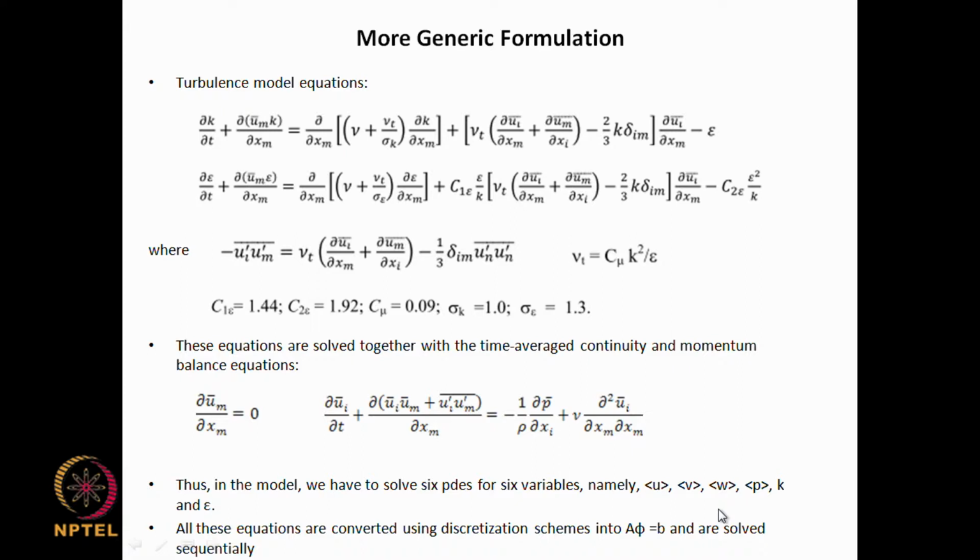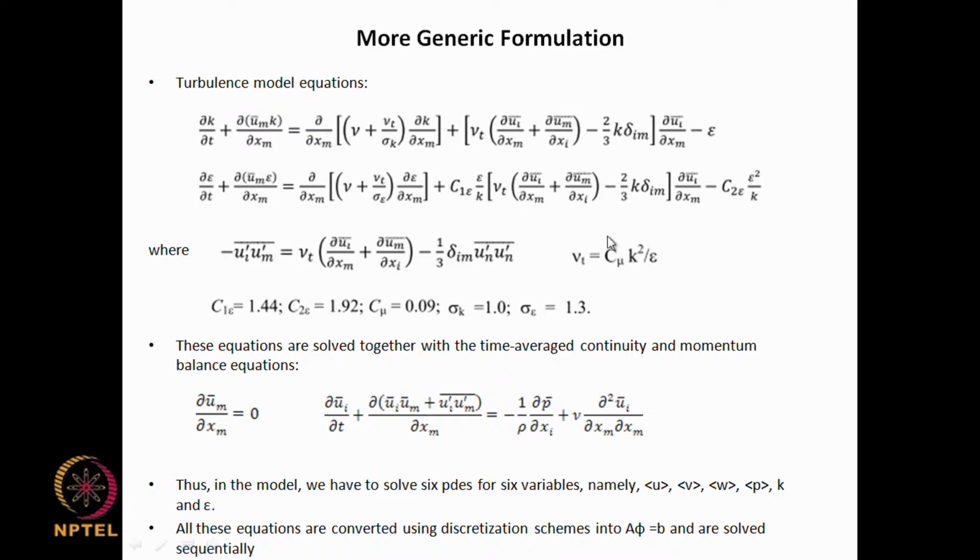So one can use an extended form of the SIMPLE method for the solution of this for typical internal flow type applications. So in this model there are no arbitrary terms, you have all these equations, and everything about these equations is specified here in this slide.